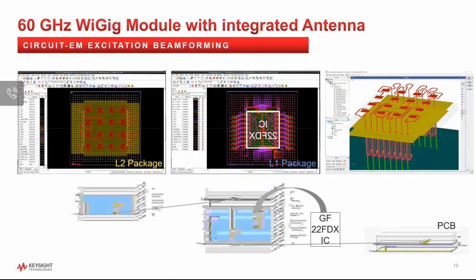In a phased array, antenna elements driven by power amplifiers will also be excited by nonlinear harmonics. These spurious harmonics can also form spurious beams in space to interfere with neighboring communication systems.